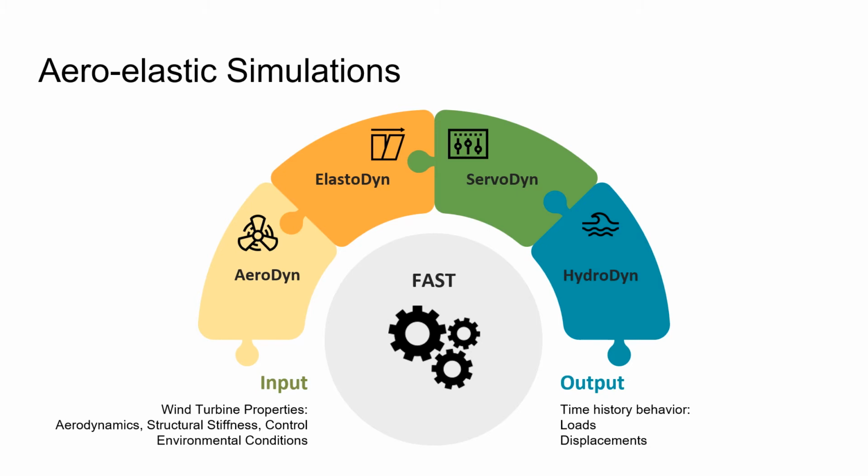As the wind turbine is represented as a beam model, the outputs are calculated in a node, not as a pressure distribution, and by default, only 10 nodes are defined per blade as a measure spot, and a total of 60 loads are extracted, considering forces and moments in all degrees of freedom per each spot.